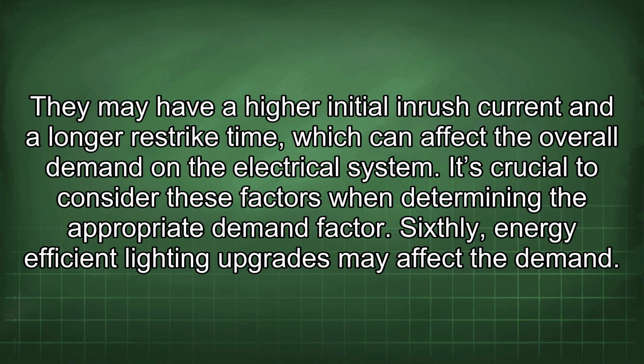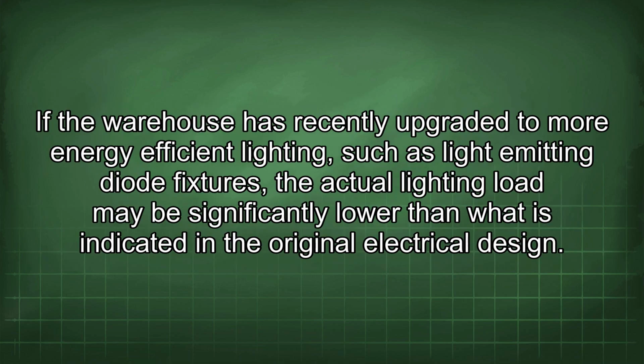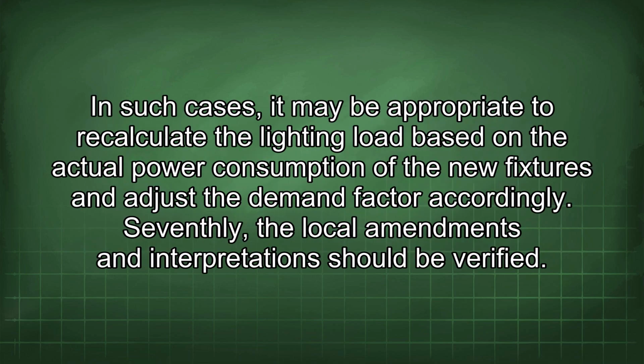Sixthly, energy-efficient lighting upgrades may affect the demand. If the warehouse has recently upgraded to more energy-efficient lighting, such as light-emitting diode fixtures, the actual lighting load may be significantly lower than what is indicated in the original electrical design. In such cases, it may be appropriate to recalculate the lighting load based on the actual power consumption of the new fixtures and adjust the demand factor accordingly.